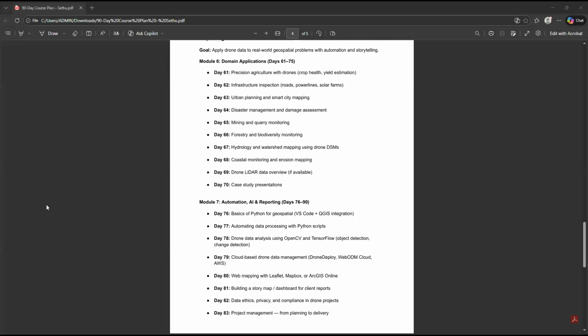So like that. For agricultural use, only three types of cameras are used. You don't mostly rely on LiDAR. You rely on multispectral cameras, thermal cameras, and regular photo cameras. Mostly this large-scale agricultural use is only in tea plantations and hilly terrains like Ooty, Kodaikanal, and other places where it is very difficult for manual survey, and the terrain is very uneven and not accessible.